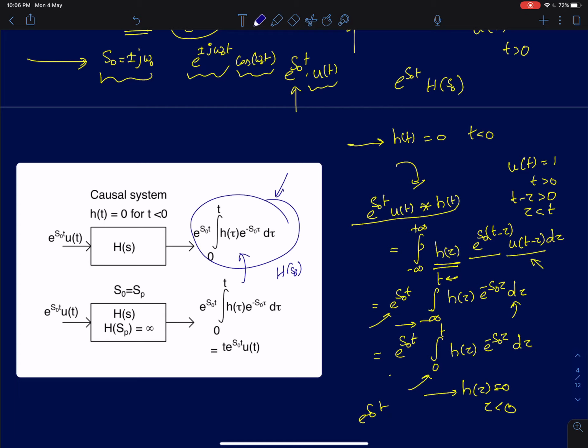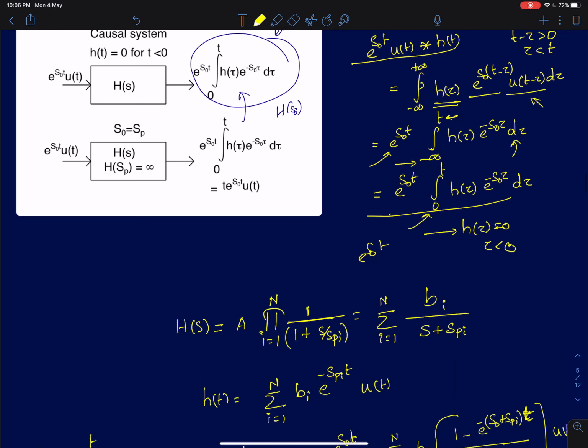So now we'll make certain assumptions about the transfer function and try to see if we can reduce this expression to some simple closed form expressions. I'll first assume your transfer function h of s has n poles. It's a pole-only system; it doesn't have any zeros. These poles can be complex, and for the time being I'm also going to assume they can be anywhere, in the right or left half of the s plane.